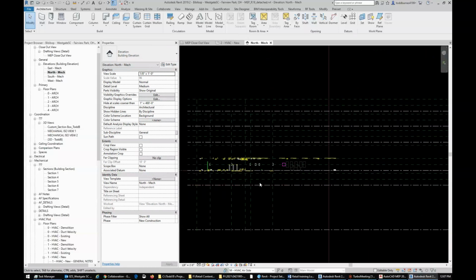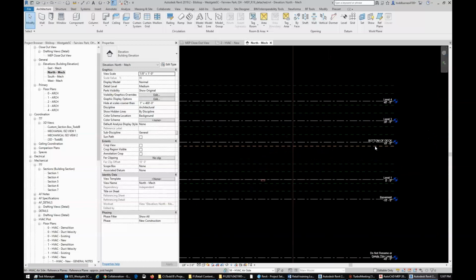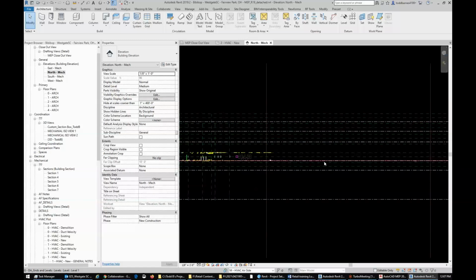Nothing is modeled up, and again, in this case, it's still beneficial to get that roof deck level situated in close proximity to what is actually going to happen. So when you put the rooftop units at that level, you've got something to reference off of and something for your views to reference. I will note again that to get these to show up correctly, it's beneficial to draw that vertical line in the Z-axis in the CAD background so that when Revit cuts a plane, it sees that there's a bit of the CAD file and it shows up with the background.